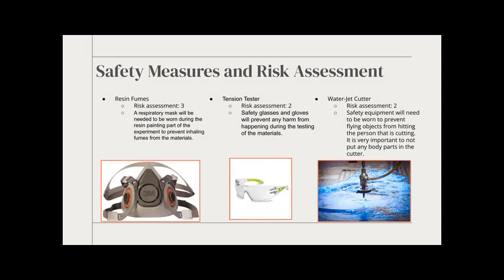For our risk assessment and safety measures, we had 3 things that we focused on that were part of our project. And number 1 thing was the resin fumes from the resin. We just counterbalance this to be safe by wearing respiratory masks and gloves and safety glasses, and we had nothing to worry about with those items on.